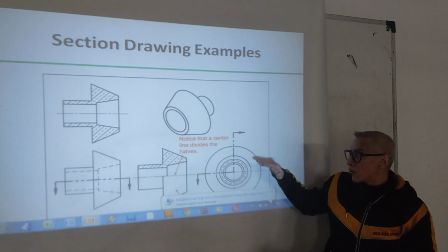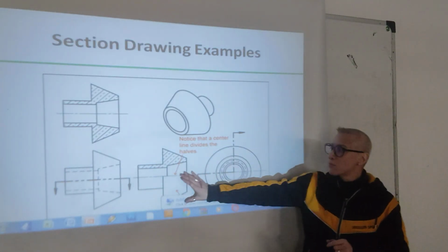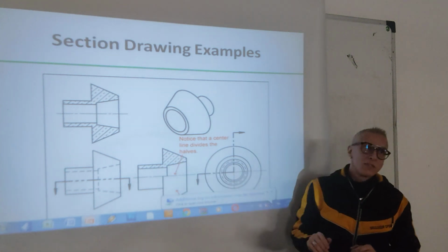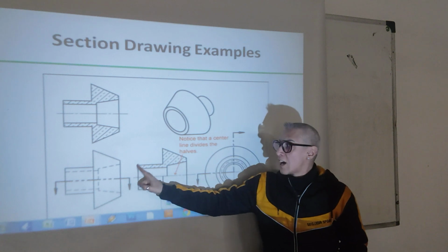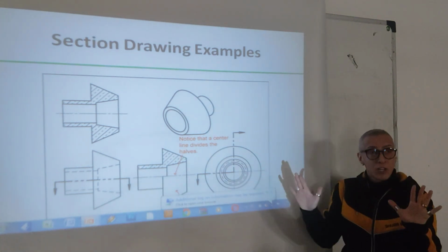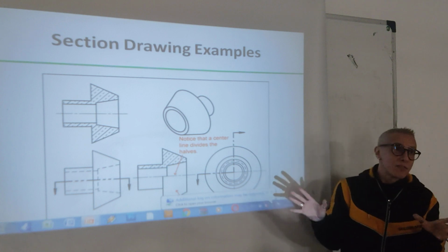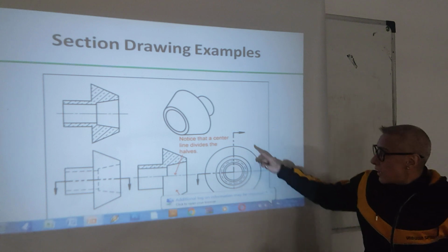But the drawing is aligned like always. You're just showing it one time closed, one time opened. And the only new thing is really putting the dash at 45 degrees to show which material is full, and which material is opened will be left as it is. So this is basically the new thing.